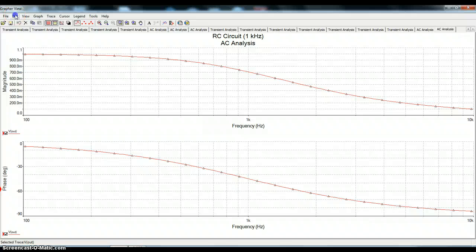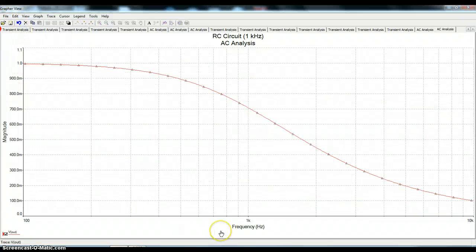So I'm going to go up here and edit, and I'm going to delete that graph. And now this puts the entire screen for the amplitude response. And you can see on the linear vertical scale that as the frequency goes up, it starts out with a ratio of 1. That's at DC, or near DC. It's really 100 hertz. You never get to DC on a logarithmic scale.